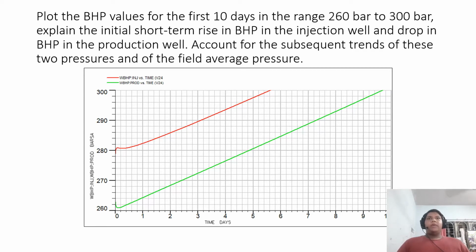This phenomenon can be identified as the pressure waves that travel in the reservoir at velocity controlled by the hydraulic diffusivity. Hydraulic diffusivity is the measure of diffusion speed of pressure disturbances in groundwater level. Large values of hydraulic diffusivity lead to fast propagation of signals in aquifer. For the graph findings above, the fast propagation signal, which is less than 5 hours, means the hydraulic diffusivity in this reservoir is quite high.